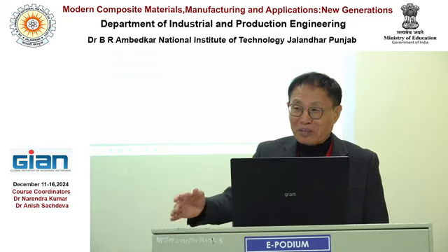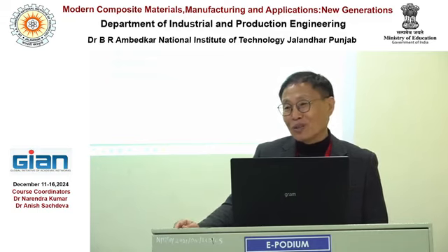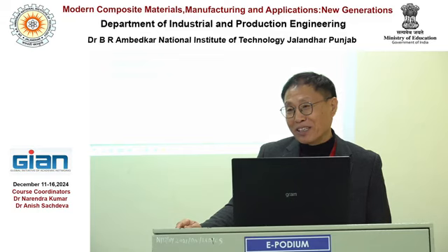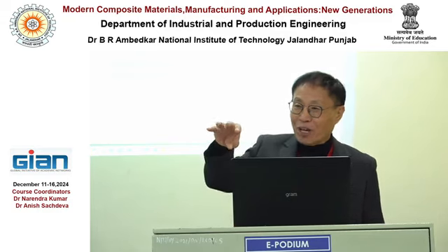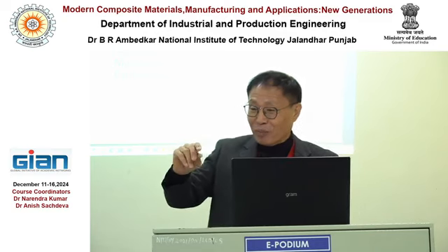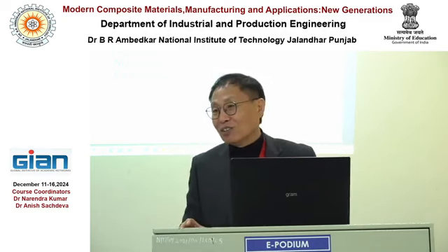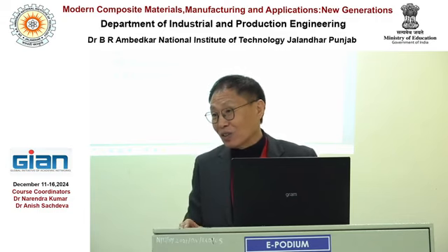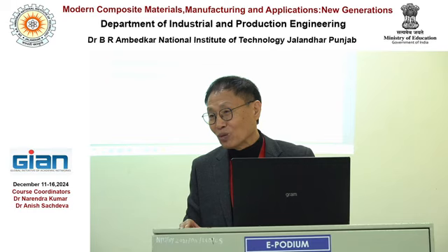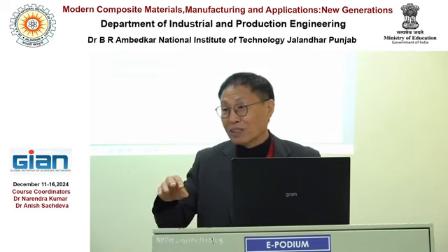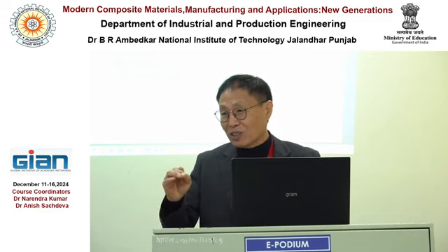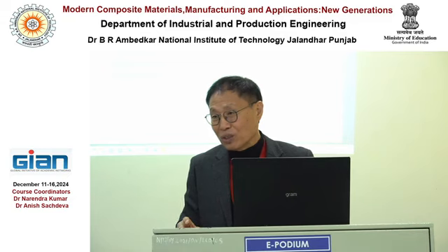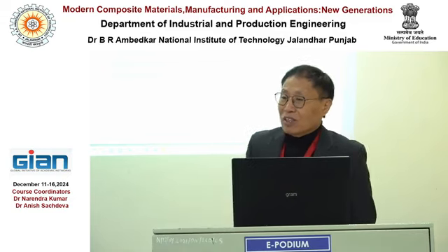Even for composites, if you wanted to use those kinds of things, you can do it. But in that case, there are many voids trapped inside, so no one wants to use it like that, because there is a fiber preform inside, and the powder must be molten into that cavity. It's very difficult to get the fiber wet. That means there are many voids, so the product will not be good.